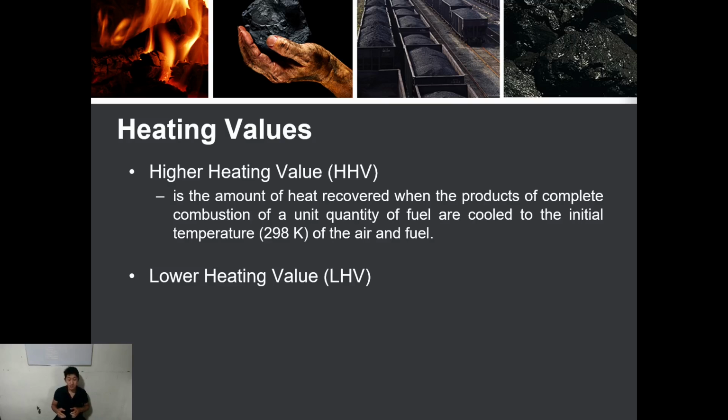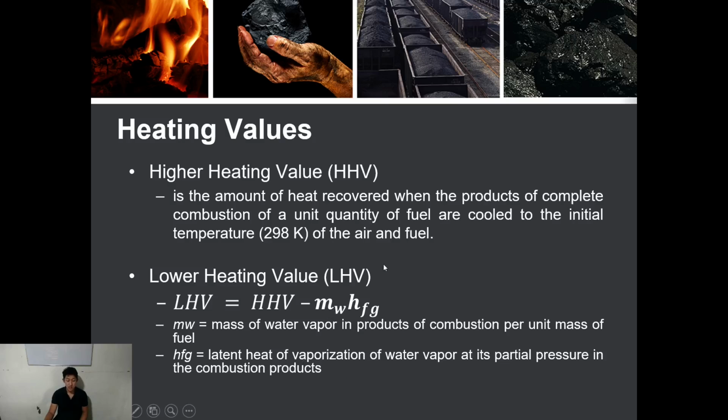If you allow these combustion gases to return back to their initial temperature, the amount of heat that we recover will be the higher heating value. The lower heating value can be obtained by subtracting the heat of vaporization. In the higher heating value, it is assumed that the water vapor in the gases condenses back to water, so it has a larger value. If you subtract the heat of vaporization of the water, you get the lower heating value.